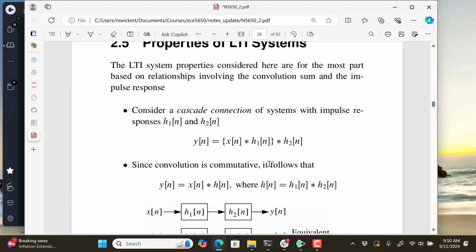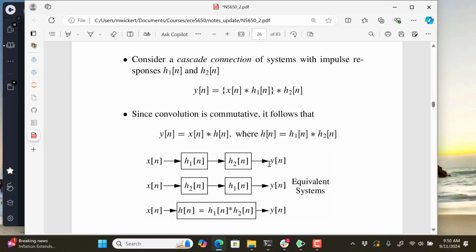You've got a function, a system, and another system following it. You can do a double convolution. First convolve the input with the first system and then convolve it with the second. If it happens to be linear and time invariant, which it is in order to have this convolution even mean anything, then we can take advantage of the commutative property of convolution, and we can change the order if we want to. So these three are all equivalent here if we wanted to view it together.